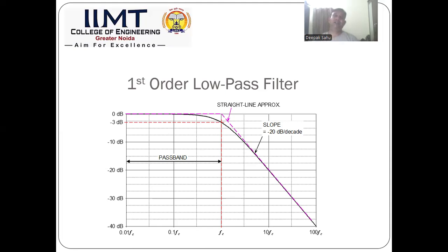This passband is the actual frequency range which will be utilized for the low pass filter circuit behavior. Any frequencies falling outside it should have sharply reduced gain. For example, at 10 times the frequency, we can see that the slope is still much higher. So this additional frequency range will incorporate noise and will disturb the smooth functioning of the filter.